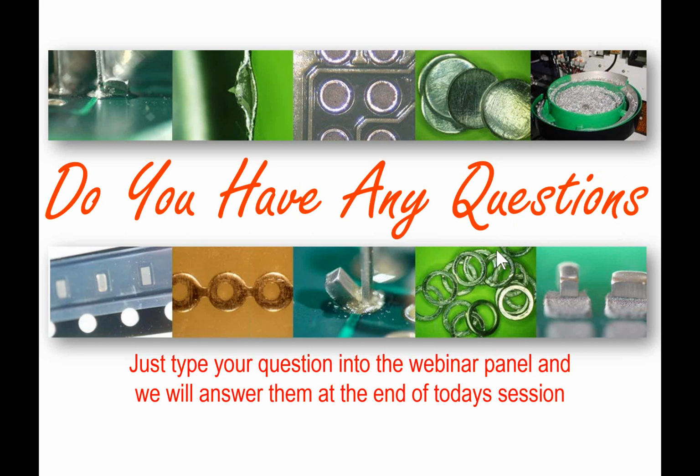obviously, if you have too long a time prior to reflow with solder bricks in pin and paste, you're going to exhaust the flux, and the flux is needed to some level to allow complete reflow of the brick. So it's a process issue, I would say. If the impression is not causing you any interactions, and again is meeting the quality standard of the solder joint, it could be just an indicator.